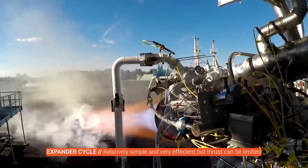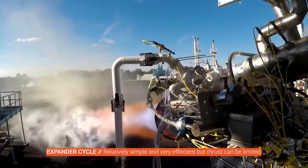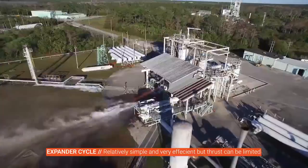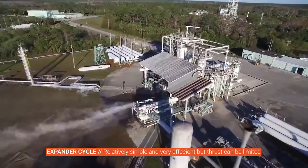Expander cycle is awesome, and has proven to be a great choice on the RL-10, but it does have its limitations on thrust output, which often leaves it off the table for a booster engine. There are also a few options of mixing and matching cycle types, like using a gas generator on just the fuel side and the expander cycle to power the oxidizer side, or some unique combinations that engineers have come up with but haven't really seen the light of day yet. But yeah, that's how you power a rocket engine.